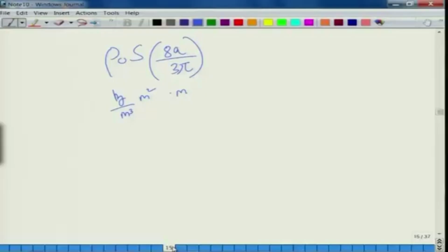So, if you have a certain tube here and you have an infinite flange here, the tube does not just end here, there is a small amount of a hypothetical tube protruding out. What is the length of such a small tube of the same radius? The radius is the same, S is the cross section area. So, the length is 8 by 3 pi, that is basically 0.85 times a. If a is very small, typically say 40 mm for automotive mufflers, we can easily work out the small protruding hypothetical length the wave would see. This is like your end correction, and we will see why this is important as far as resonance frequencies are concerned.